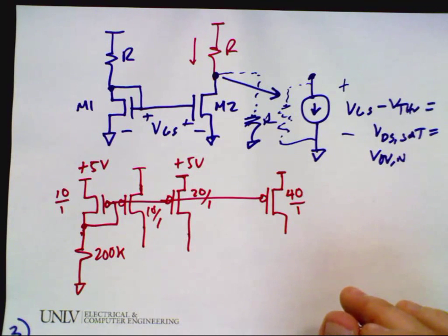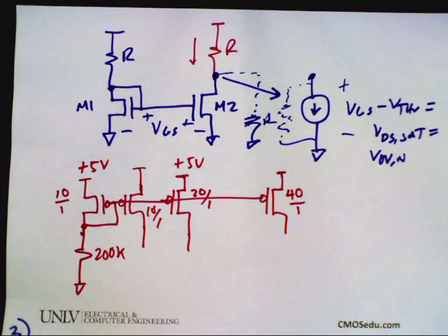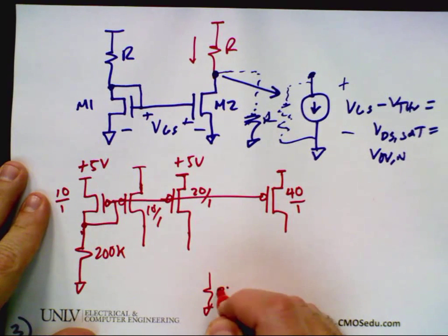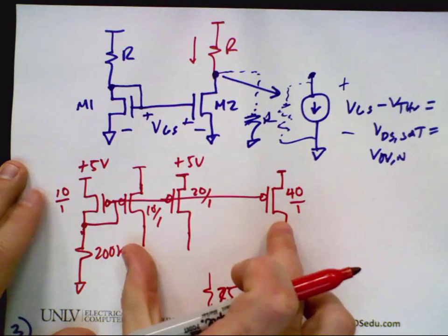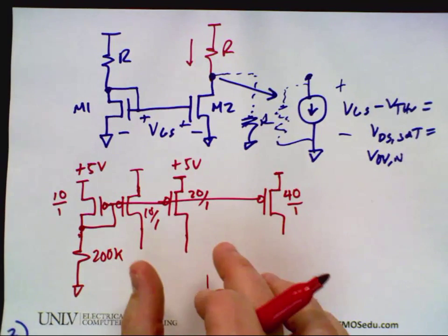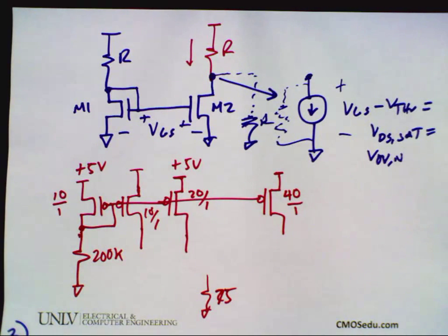In the olden monitors, the old monitors, the CRTs, if you measure the input resistance, it was 75 ohms. So there would be a 75 ohm input, and you would feed a current from your graphics card with a technique just like this to those 75 ohm inputs, and they would be differential. In other words, you would put differential current, so one would be going up, the other would be going down.